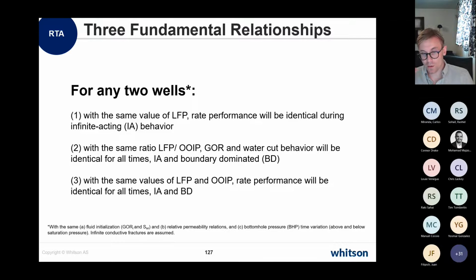The question that always comes up at that point is, what two wells actually have the same pressure versus time and rel perm relationships, etc.? And the answer to that is no wells have that. But that's why we're applying these relationships systematically, not on different wells, but on the same well. So we're applying these relationships together with the numerical model so that we can do RTA with the numerical model. Just to remind ourselves that these things are true.